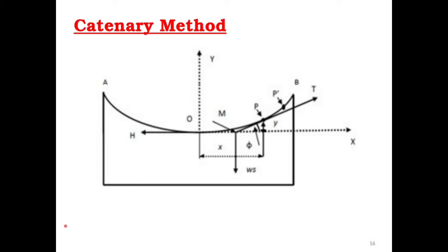the sag. Now I'm coming to the next method, which is called the catenary method. We talked about the parabolic method, meaning when we have a conductor of uniform weight distributed along its line length, and we suspend it freely in between two supports that are at plane level and of equal heights. The lowest point of the conductor happens at the middle point of the span.